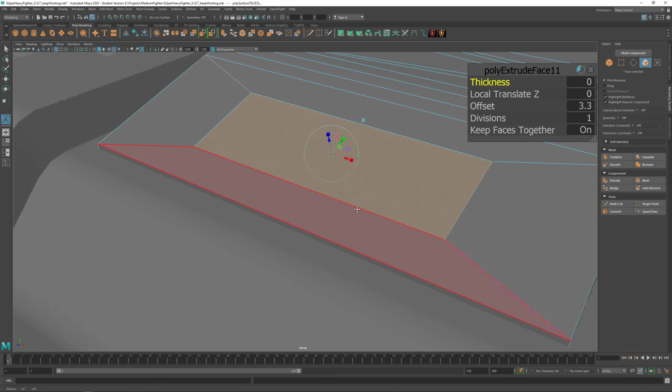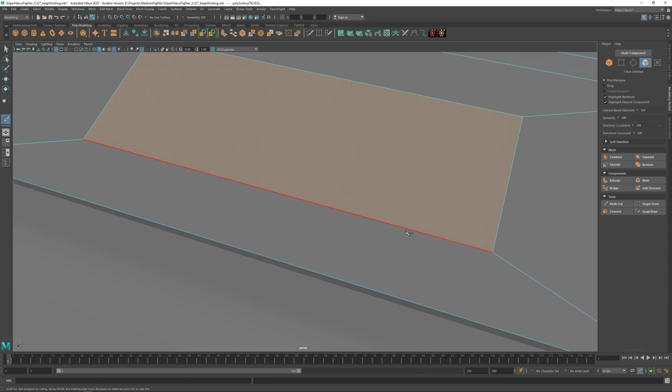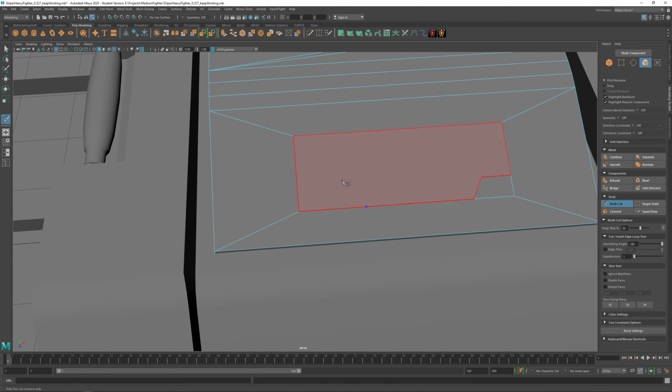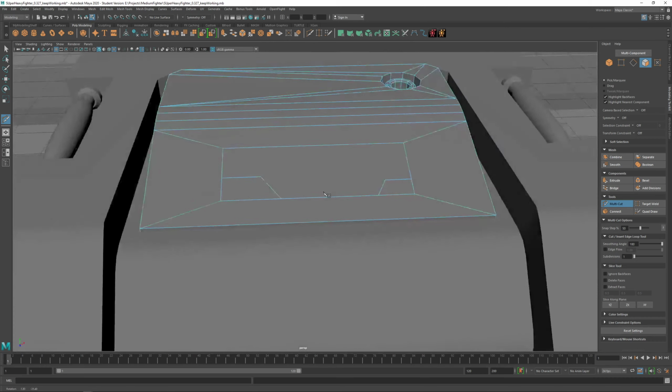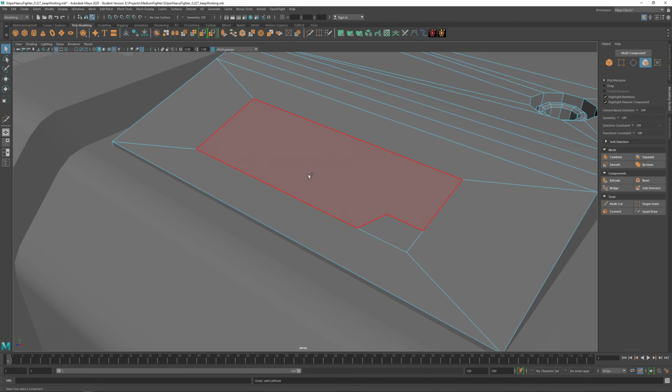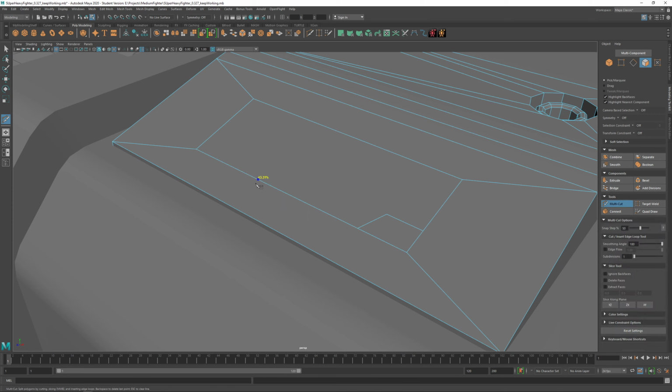No, I'm going to carve this a little bit because it's too simple. So just make it more sci-fi, you know, angular and stuff. So again, I use multicut with clicking, click, and then Control Shift to make it a 90-degree angle.